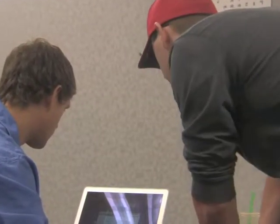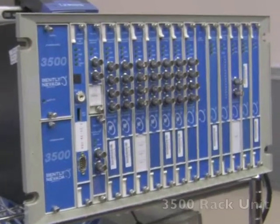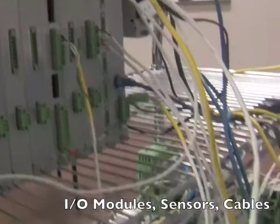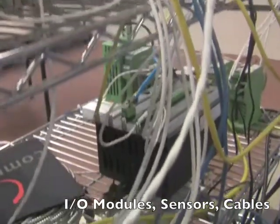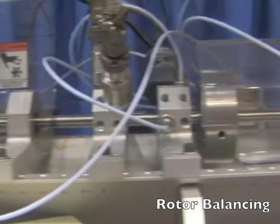We worked closely with General Electric to develop a product that provides support for the 3500 rack unit, cross-validating various components such as probes, I/O modules, and cables being installed, as well as to provide rotor balancing. And all of this on a device that you can fit in your pocket.